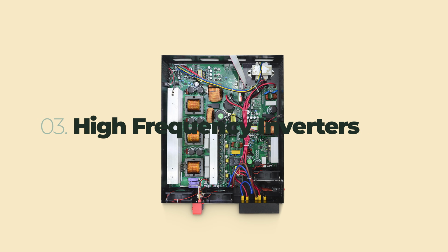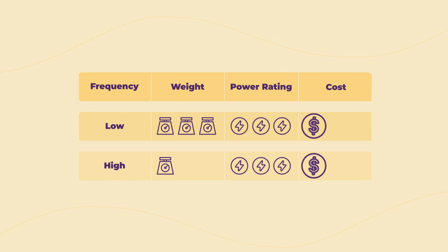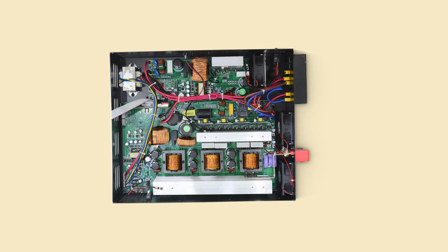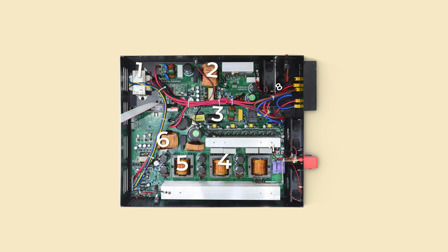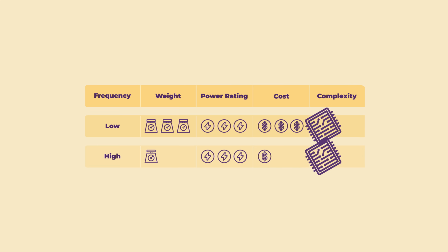High frequency inverters are often much lighter, smaller and lower in price than a low frequency inverter. However, to achieve this, they generally have an increased component count of smaller components, which leads to increased design complexity. In a high-end brand, this does not cause issues and you'll see longer warranties. But in low-end brands, this generally leads to more points of failure and, again, shorter warranties.